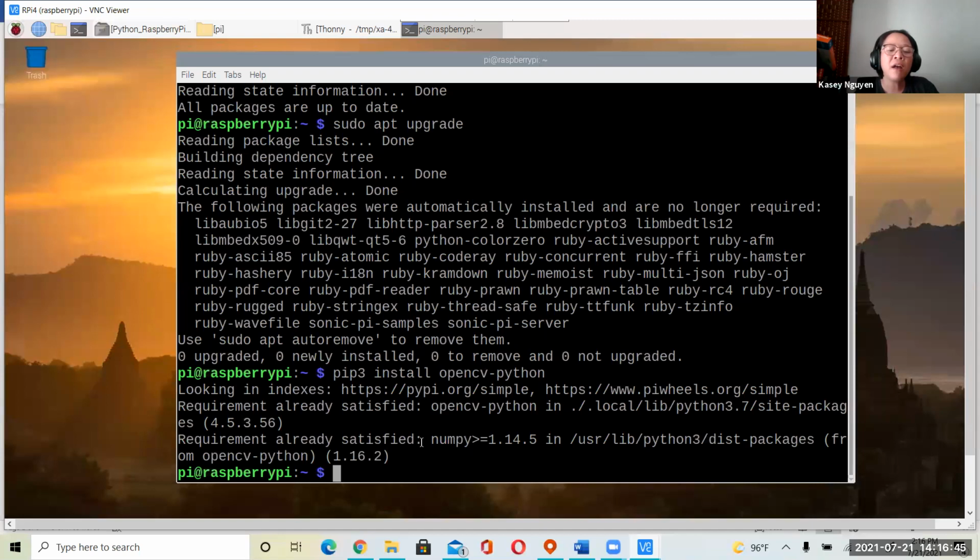If you have not installed it before, it's going to take close to a minute just to get everything. If it asks you if you want to write this into the drive, which is your SD card, you want to press Y for yes. There will be several packages that we will pull that will require your drive space, so make sure that you answer yes, Y, to get it downloaded and installed.